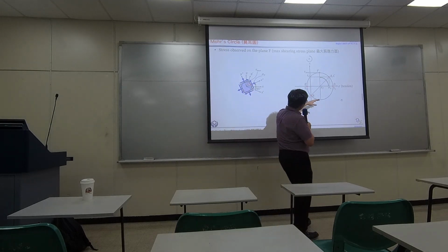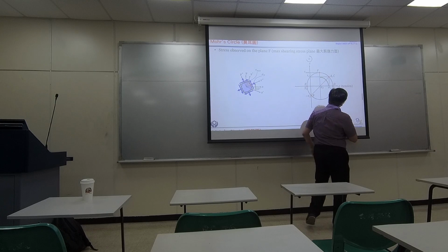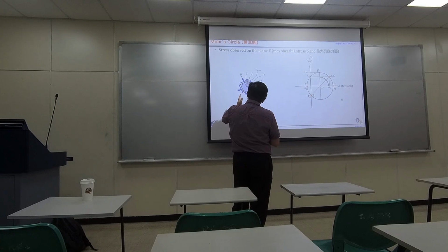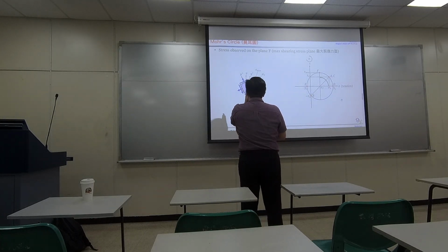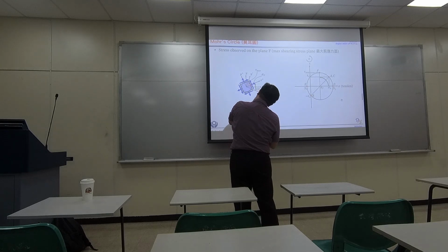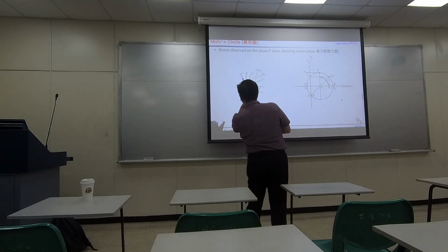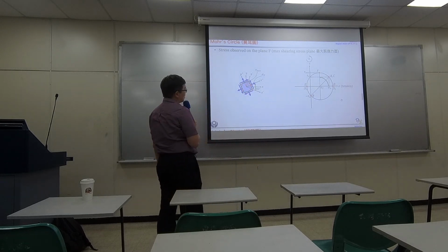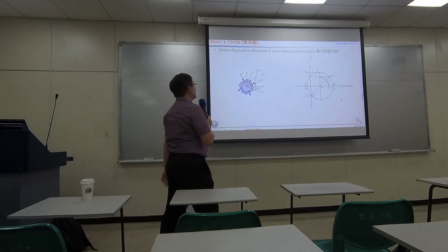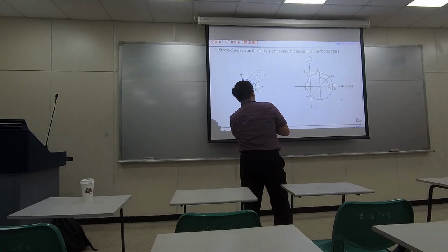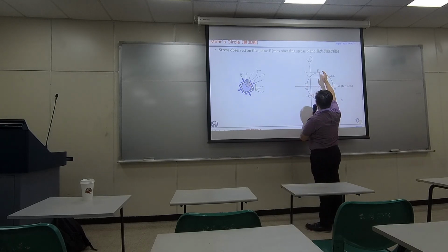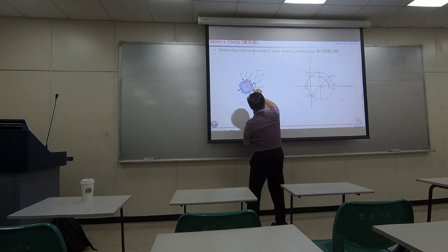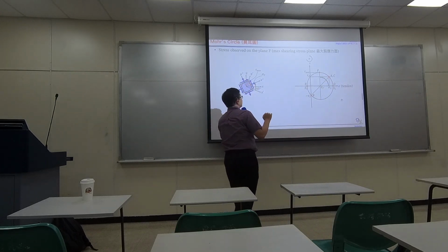So when we rotate by 90 degrees in this Mohr circle, that means we need to do some rotation here again. Earlier we were straight, and we bend our head by theta. Now we're gonna rotate back by 45 degrees, and it turns out it's a new way of observing the same point. But along this direction, we realize we have the largest shearing stress of this element. So over here, our shear is the largest.